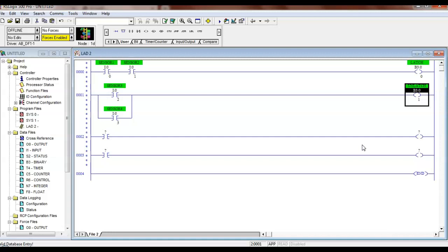Why would we use a coil that's never going to generate an output? Because, and that's a good question, because in a major control logic, 90% of the relays are in there to make decisions. They don't turn on outputs. They don't do anything. They just make decisions.